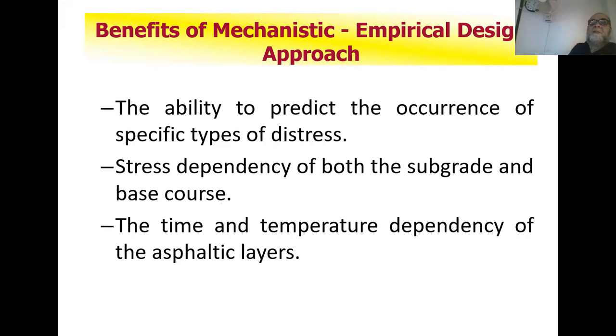Now, what are the specific types of distresses? It means to control fatigue, to control rutting, and there is another distress, low temperature cracking, in places where you have temperatures most of the time in the year below 0 degrees centigrade. So those methods are also being used to design a pavement, or to verify the pavement against these distresses.